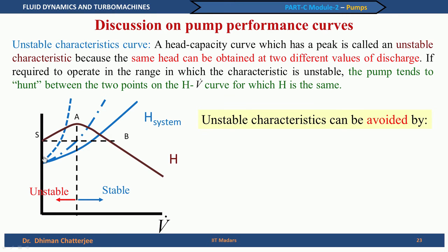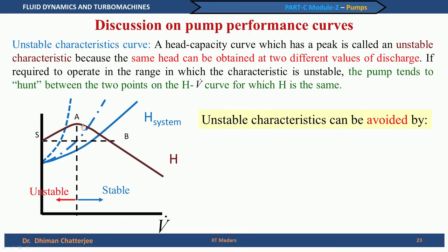How do I understand it? Let us say this is my system curve and I am throttling a valve, so that the resistance increases. Between this point and the next curve, what we see is, as the volume flow rate reduces, the head developed by the pump increases. So, as you have throttled the valve, the volume flow rate will reduce, the head requirement from the system increases and the pump is in a position to supply the extra head. But you imagine that you are crossing this point A, that is you are throttling further, using a valve and closing the valve further.